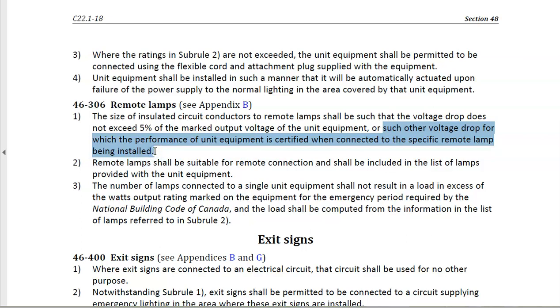On our old incandescents, those halogens, they were big and bright and took a lot of juice. Now with all of our LEDs, we can go and connect these things in a lot of cases, in a manner that we're going to have sometimes like a 20 or 40% voltage drop, and they're still going to be fine because most of those are dropping it down anyways inside of there.